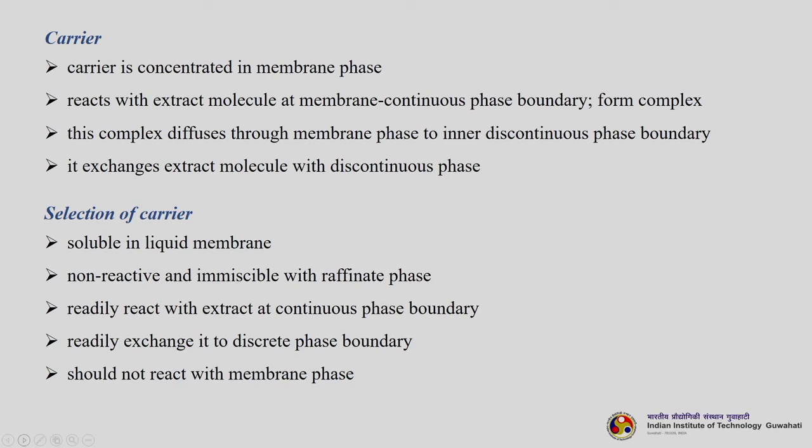reacts with the extract molecule at membrane continuous phase boundary, form complex. Now this complex diffuses through the membrane phase to the inner discontinuous phase boundary. It exchanges extract molecule with discontinuous phase by virtue of the concentration difference again. Now selection of carrier is a very important parameter, which carrier to be chosen.